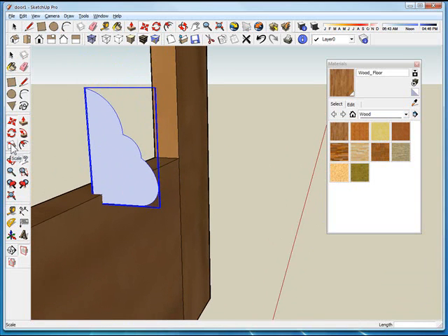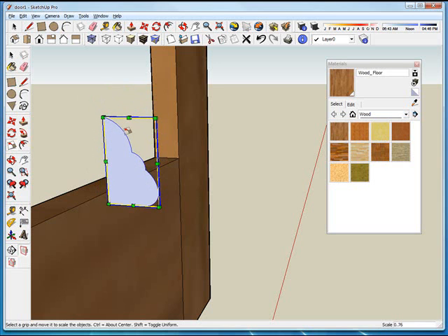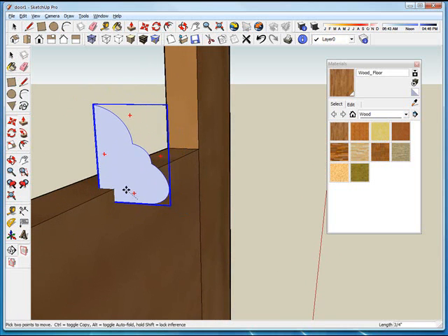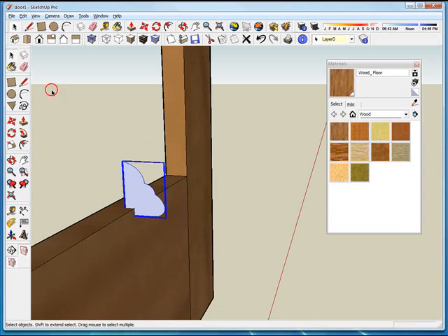And you can thumb around and do it different ways and manipulate it different ways. It's kind of fun. Now in that position, I'm going to reshape it because I think it's just too big for going around my door. So I'm going to use this scale tool, and you'll notice these handles pop up. It allows me to rescale the item pretty quickly. I'm just going to rescale it down right about there. Okay. Now I'm going to click it one more time and drag it into my door about that far. Okay, now with that complete, I am going to right click on the item and explode it so it's back into the regular pieces that we find in the SketchUp model.